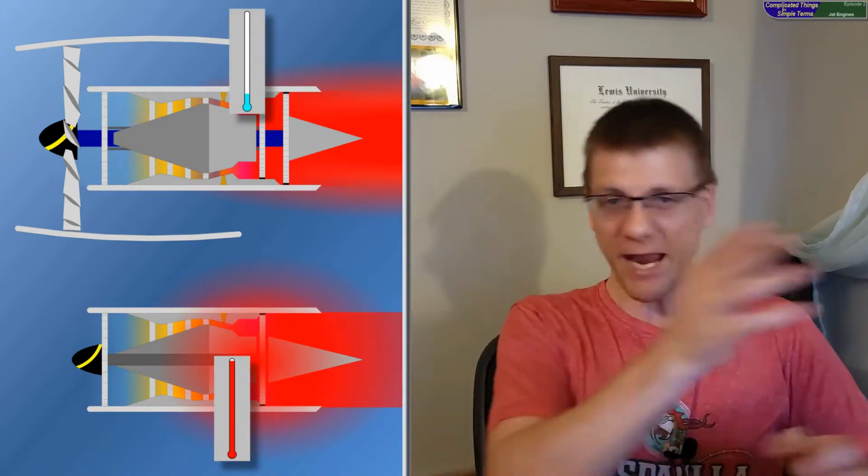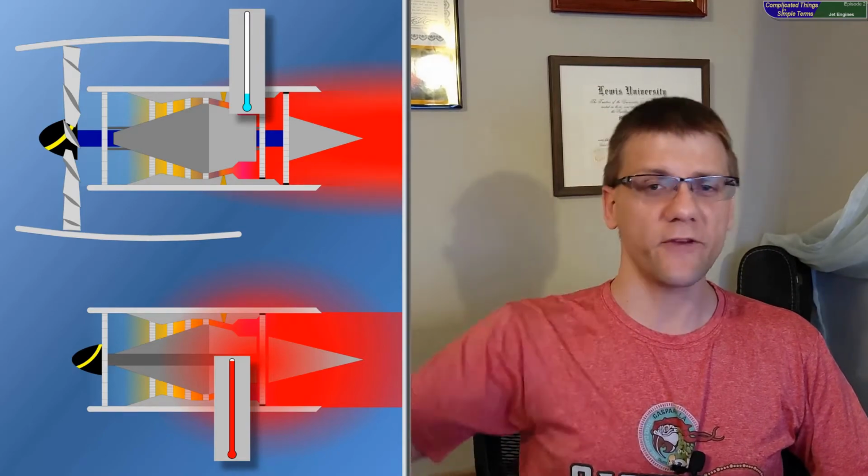It'd be difficult to keep it cool because it would just be sitting there on the ground. And if the plane was taxiing for a long time or just stuck on the ground, the engine would experience a much greater range of temperature change than you really want. Well, with a turbofan, you don't have that problem. The hot central section of the engine is always being cooled by this big wash of air that's going past it in a high bypass turbofan, and that air is just coming from the big fan at the front of the engine.